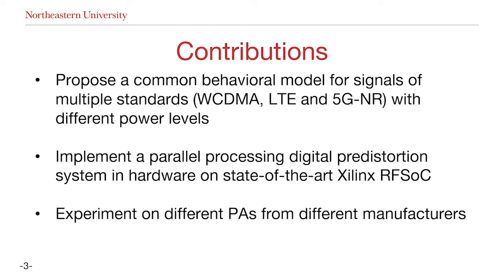After proposing the model, we implement a real-time DPD system on the FPGA, the RF-SoC from Xilinx, which increases the power efficiency of our system. The state-of-the-art Xilinx RF-SoC has 16-bit data converters with a 10 gigasamples per second sampling rate. Our parallel processing DPD system allows us to match the speed of this next-generation RF front-end.